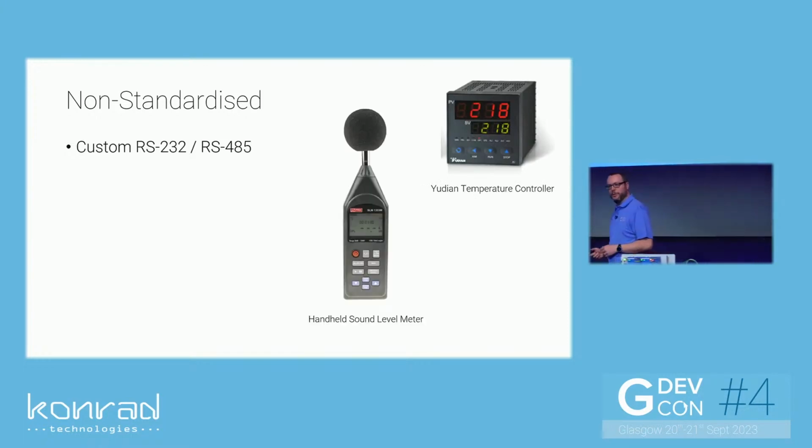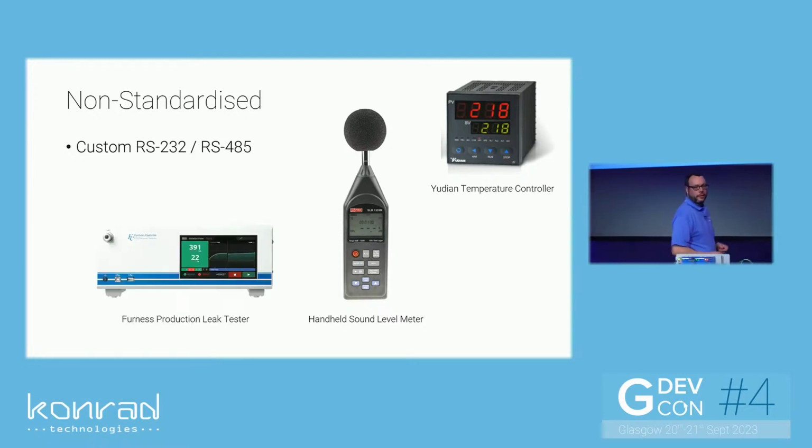Terribly integrated temperature controllers, handheld sound meters that as an individual device are actually really clever. But as soon as you plug in that RS-232 interface, you're in for a world of hurt. And that product there, an exceptionally good leak tester device, standalone, benchtop, programmable. And again, it has a serial interface, and you'll be up late trying to get that to work reliably. So you don't want RS-232 with a non-standard protocol if you can help it. It'd be much better if the manufacturers actually adopted one of the more standardized industrial comms.